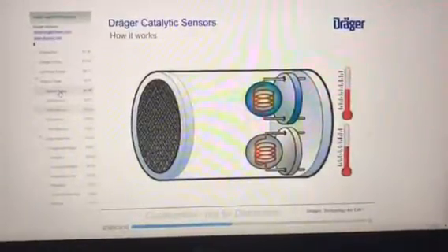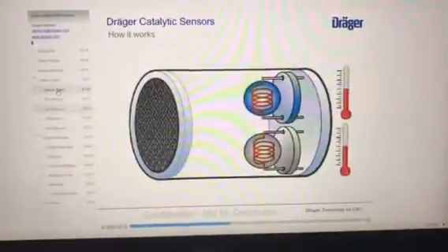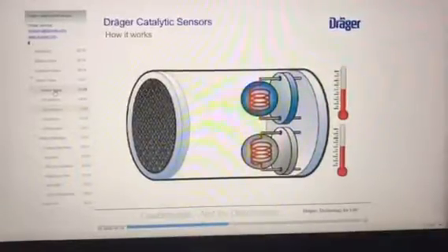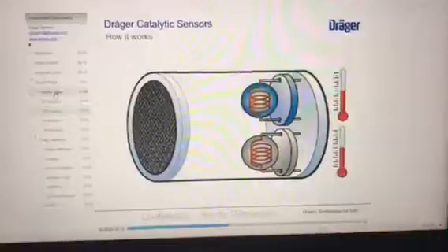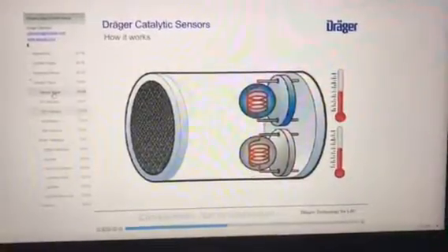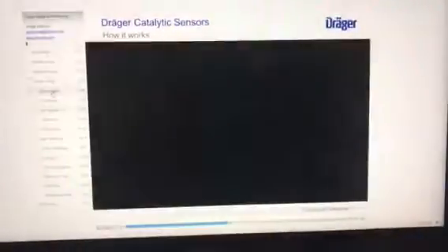With Draeger monitors, if the O2 concentration drops below about 8% by volume, the reading for the combustible sensor will be blanked out. Once the O2 levels come back above 8%, the combustible reading will again be displayed.